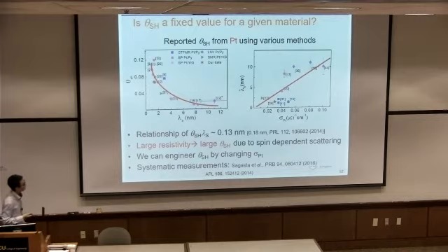And this indicates basically a large resistivity material. Even though it's the same material, if you can tune your grain boundary, annealing condition, or argon pressure during deposition, basically you can change your material parameters like resistivity. Then a larger one will give you a large effective spin Hall angle. So this is kind of a rule of thumb. And this is due to spin-dependent scattering.